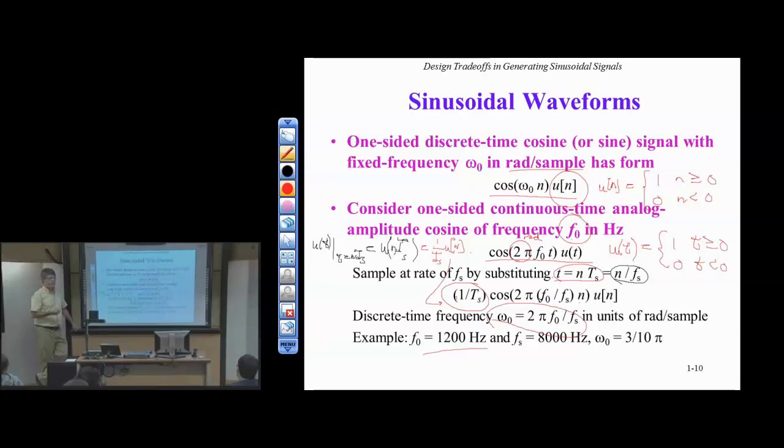It's okay if this bothers you right now, but the gain is something we are going to allow to vary, and we're going to just change it when we want to. I know it sounds a little bit weird. In any signal processing system, the gain is something either the user controls, like turning up the volume when you're playing audio, or the receiver in the system automatically adjusts anyway through a process called automatic gain control, which we'll talk about after spring break.